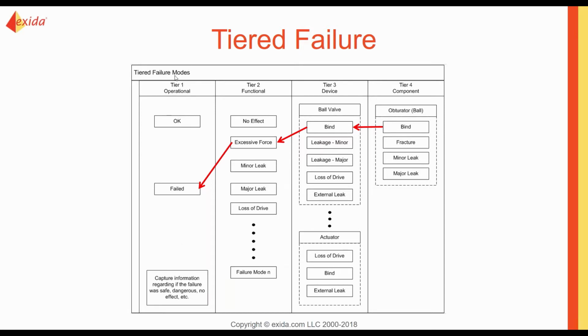61511 can be at a higher level, like operational, a little more clarified than just okay or failed, but more that, okay, the valve needs to close. And we need this functional view of what this final element needs to do in greater detail, and we need to specify that to move past this area where we're seeing failures in performance that we don't like.